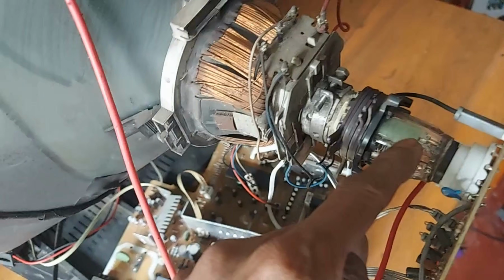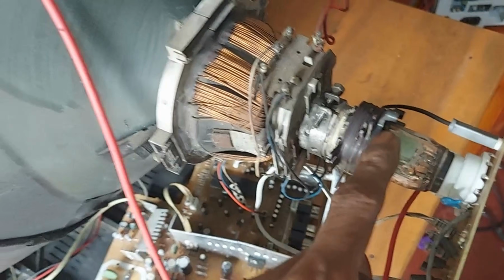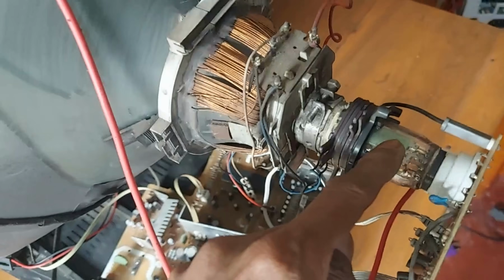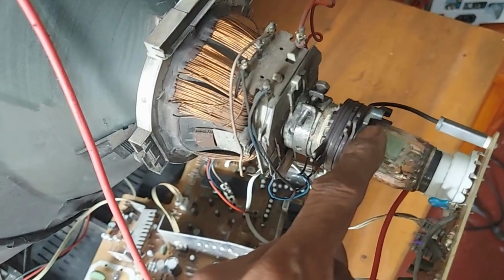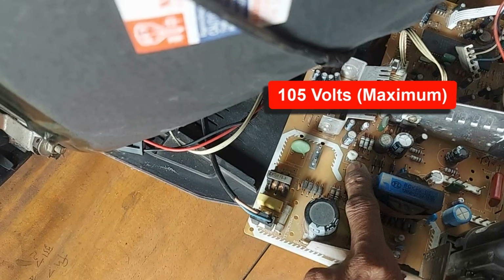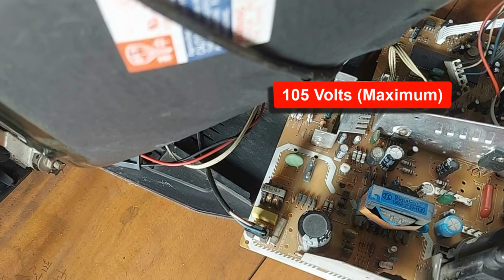But if the voltage is increased, then the filament voltage crosses the limit, the EHT current overflows, and the cathode emission increases. As a result, the picture tube is quickly damaged. So, I recommend keeping the maximum voltage to 105 volts.